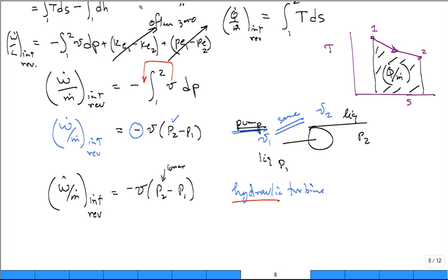A lot of times students look at this and say, look, I learned work is equal to F dx. I multiply by area, I divide by area. That's equal to pressure, force per unit area, times a change in volume, PdV. I understand work is equal to PdV. Now you're telling me work looks like V dP. What? It looks backwards, doesn't it? That was for a closed system.